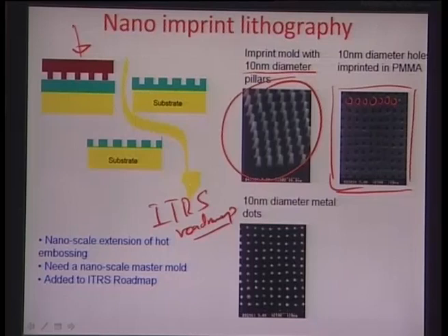So, this can be used as a shadow mask for processes like deposition, where this mold is put over a wafer and material like gold or platinum is deposited through this shadow mask, so that these tiny dots here are each of about 10 nanometers in diameter, because they can go through this particular hole on the PMMA. So, the shadow mask is later removed and you have an array of these fine dots, and these are used off and on for a lot of micro nanoscale electronics.